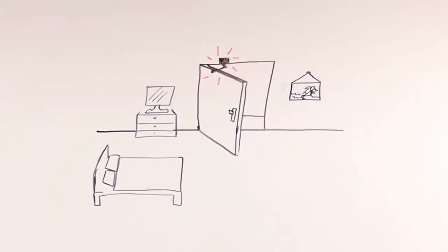A self-closing door has a door closer or spring hinges, which close the door each time it is opened. Hold-open devices for fire doors must allow the door to close automatically when smoke is detected. These are called automatic closing doors. A fire door may also have an automatic operator, but the operator must be disabled during a fire, and the door will then become self-closing.